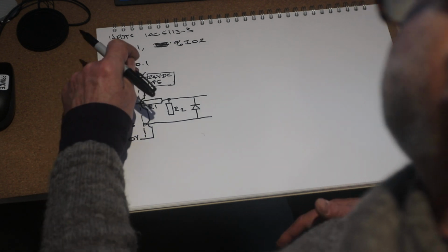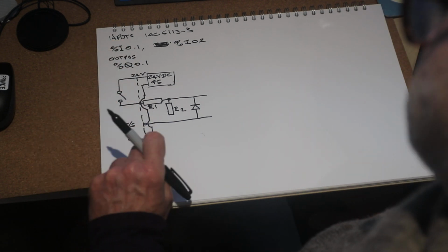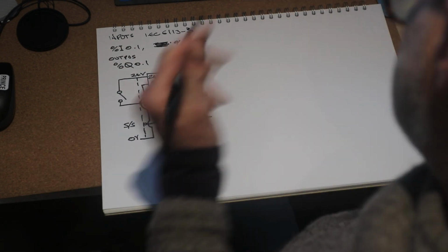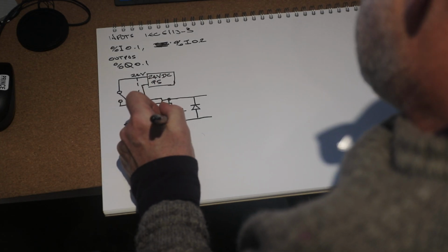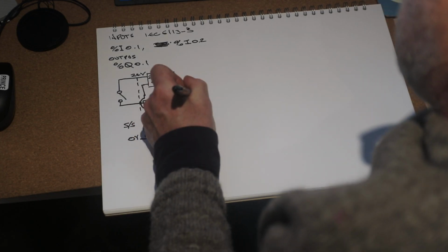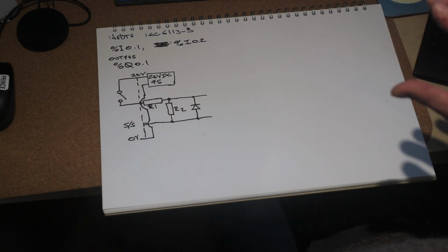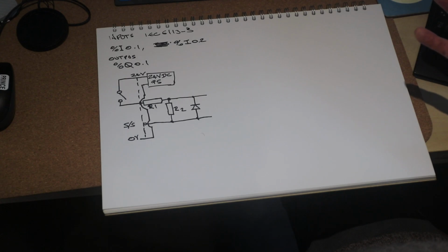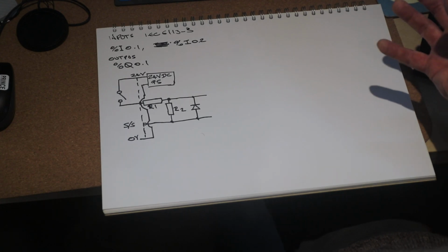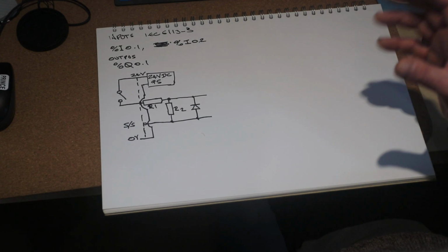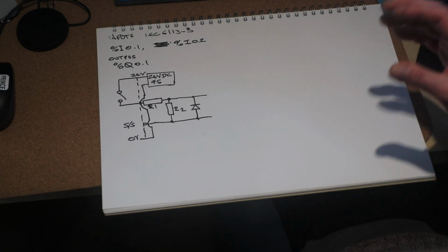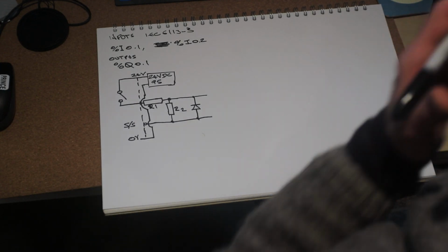So I could connect sinking and sourcing to 24 volts. I could connect it to 0 volts, and I'm not going to get very far unless I connect R2 in there. And sinking and sourcing would work no matter what you connect it to? Yeah, it's just, we're going to talk about the actual transistors that you could use, the sensors that we could use, and some of them are sinking sensors and some of them are sourcing sensors. We're going to talk about them in a minute. Cool.